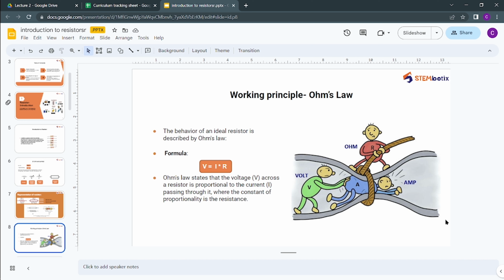So you can say the network or this connection has the total resistance this way. The inverse of R total, the total resistance of the network, will be equal to the summation of the individual inverses of resistance. So in parallel connection, the resistors share two or more common nodes and the voltage across each resistor is the same while the current is different.